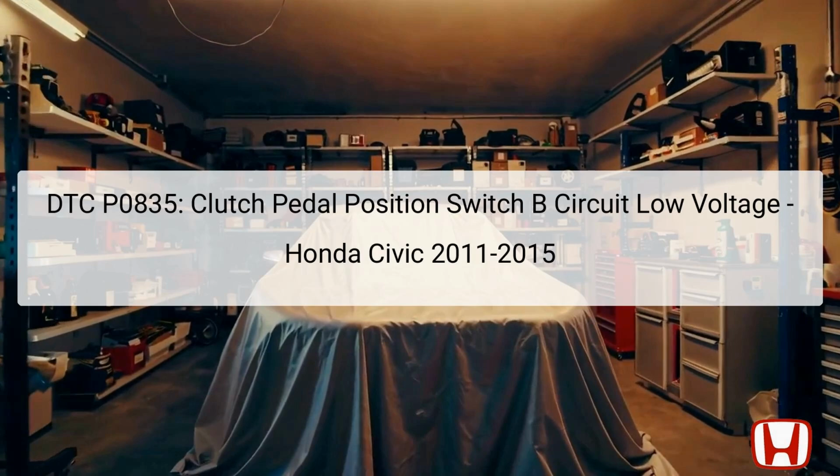The Diagnostic Trouble Code, DTC P0835, indicates a problem related to the clutch pedal position switch B circuit, specifically pointing to low voltage in its operation. This switch plays a crucial role in determining the position of the clutch pedal within the vehicle's transmission system. It ensures that the engine can engage or disengage from the transmission based on whether or not the driver is pressing the clutch pedal. Its location is typically found at the clutch pedal within the driver's footwell area, directly linked to the vehicle's engine control module, ECM.